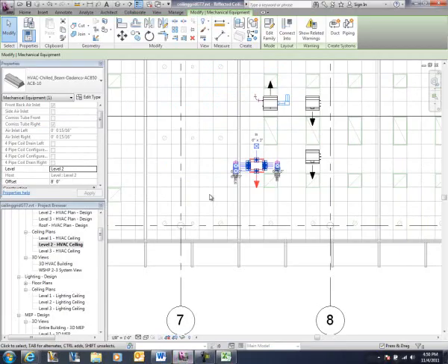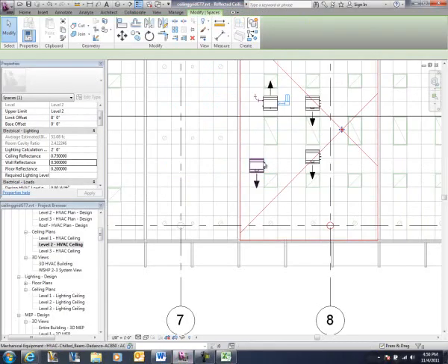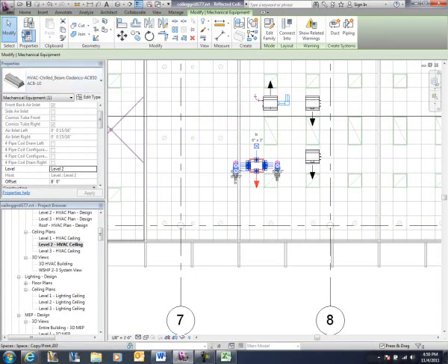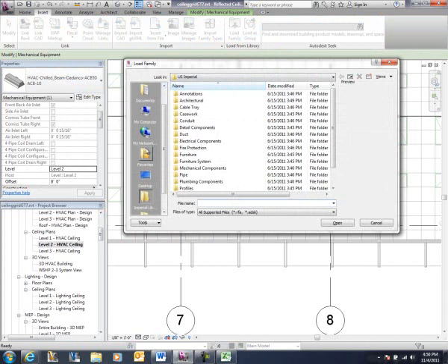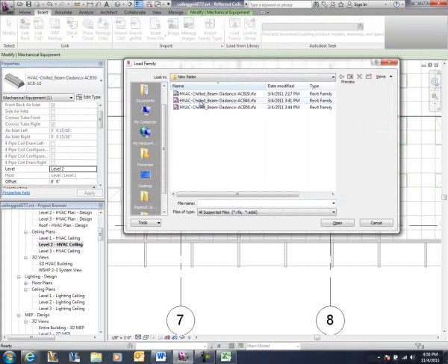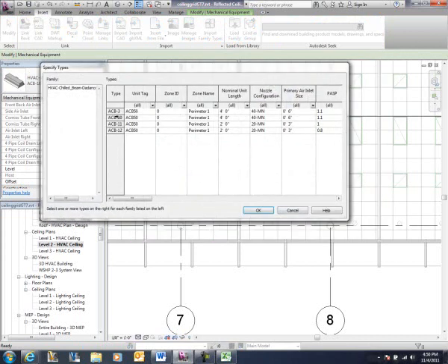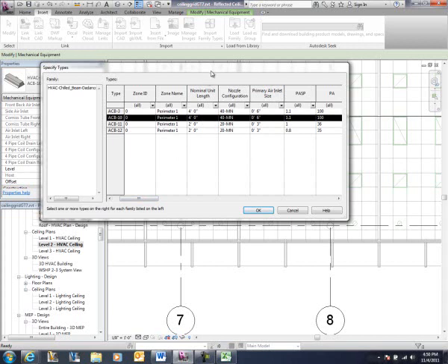And then if I go back to my Revit file, here's my ACB 10, and you have to reload these families. My documents, where did I put this? When it was an ACB 50, I think it was ACB 10 we said, right? So now you see this is going to be a 4-foot unit.